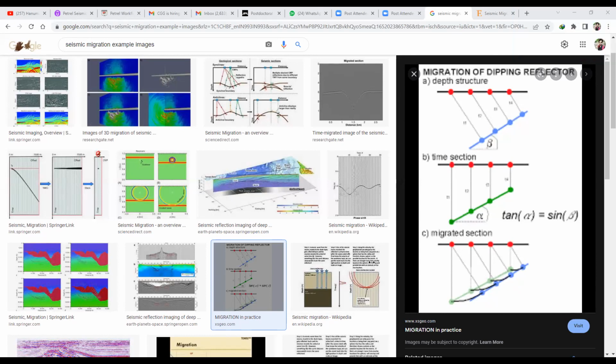No, elevation correction is different. Elevation correction is for the topography, the top of the surface, not the subsurface. It is done for the top surface, where the geophones are planted. But migration is considered for the subsurface.